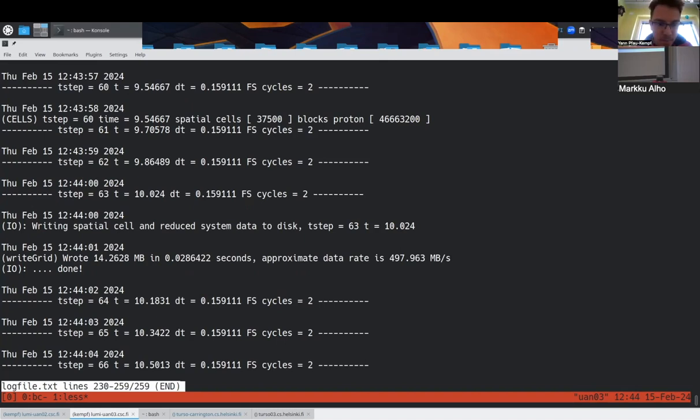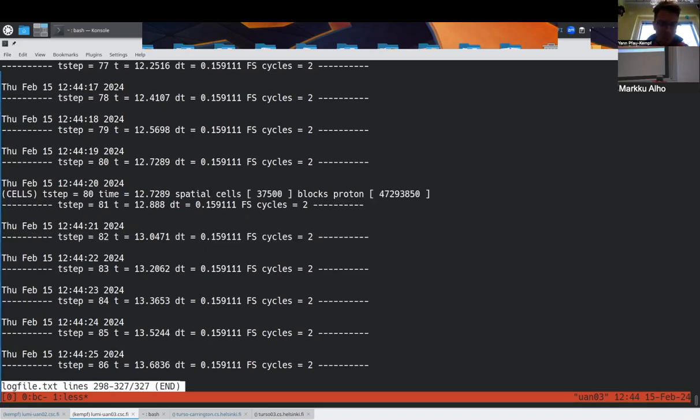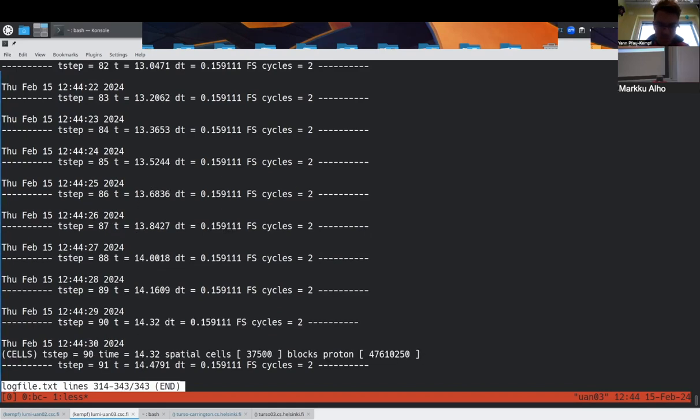Yep. So you said that we need to initialize the simulation. We need to set the upstream and downstream conditions according to Rankine-Hugoniot. But in the DAT file, you only put the upstream conditions. Doesn't the code itself use those conditions to calculate the downstream values according to Rankine-Hugoniot? So from us as users, do we have to put upstream and downstream?